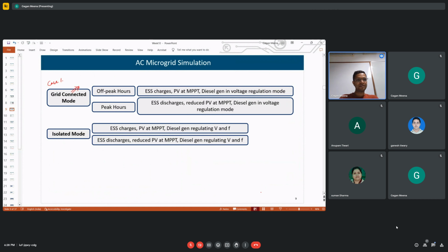This we want to minimize, or we call it smoothing the current. Smoothing the current waveform, we add these filters. L filter, LCL filter, both are able to provide this smoothing of current. So it will reduce this ripple and it will be very small.